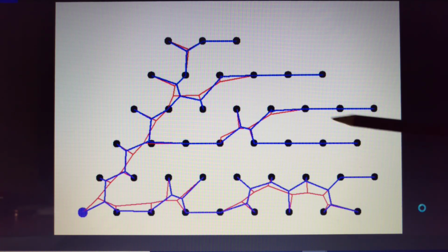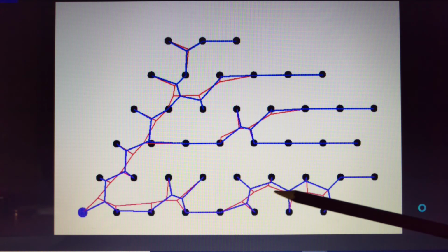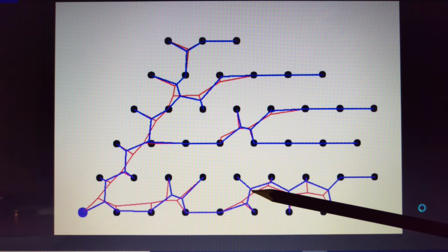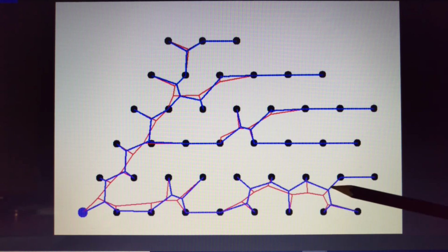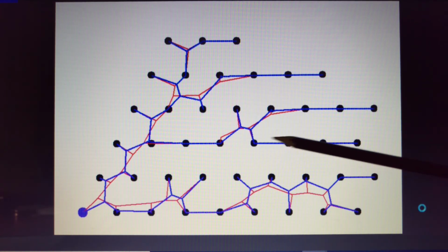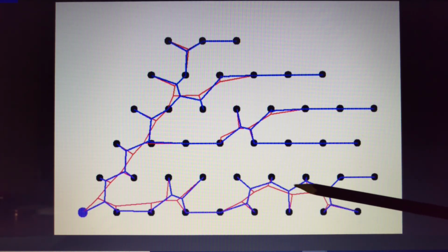The reason I made changes here and here is just to show an example where you may not want to do this kind of thing, for practical in-the-field reasons due to difficulties in laying out these lines, with more connections here and here versus going straight across. You can do it either way. This type of optimum will save a little distance, but maybe you'd want to do this. The point is, this is a tool. Don't be afraid to make some manual changes, make multiple runs, and see what your lengths are.